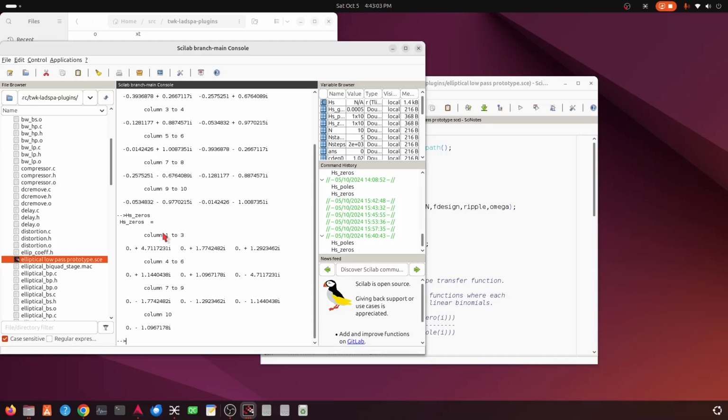The smallest rational polynomial factor with real coefficients is a rational of 2 quadratic polynomials, or a biquad. The numerator is the product of zero conjugate pair binomials, and the denominator is the product of pole conjugate pair binomials, as shown in the comments.